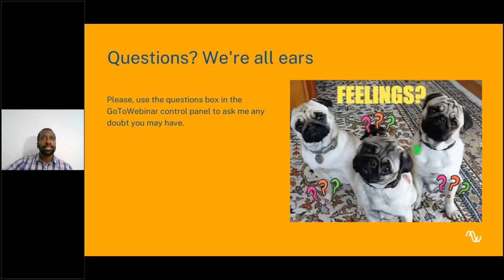Someone is asking if we can upload a LiDAR for the topography. So the answer is going to be yes, you can. You just need to make sure that you have the coordinates that RatedPower will need, and those will be X, Y, and Z data. And you also need to ensure that the size of the file does not surpass the 500 megabytes allowed for your topography data.